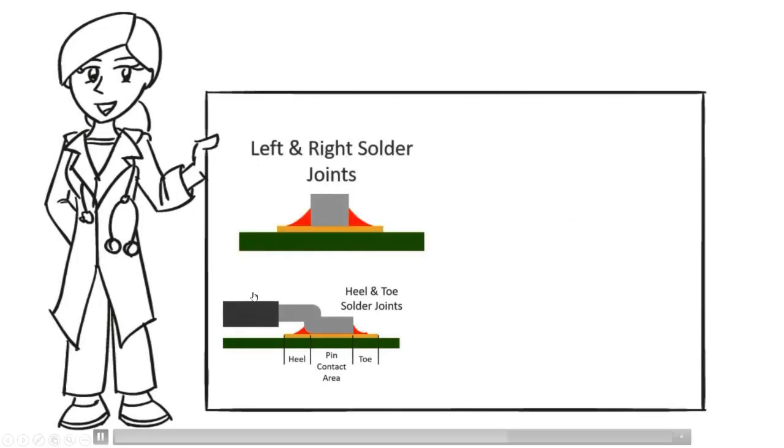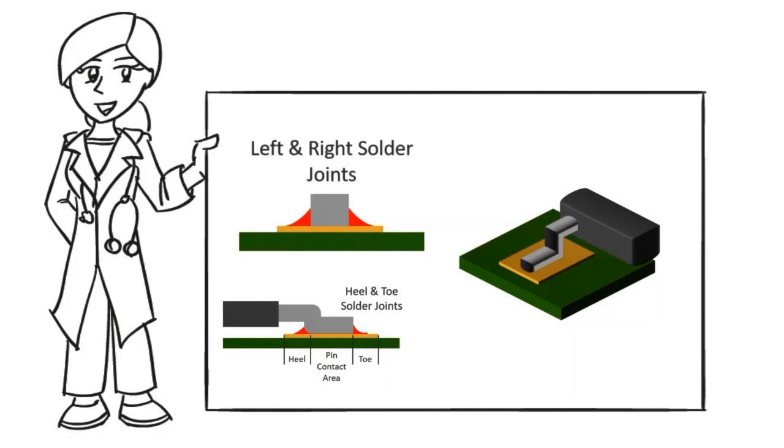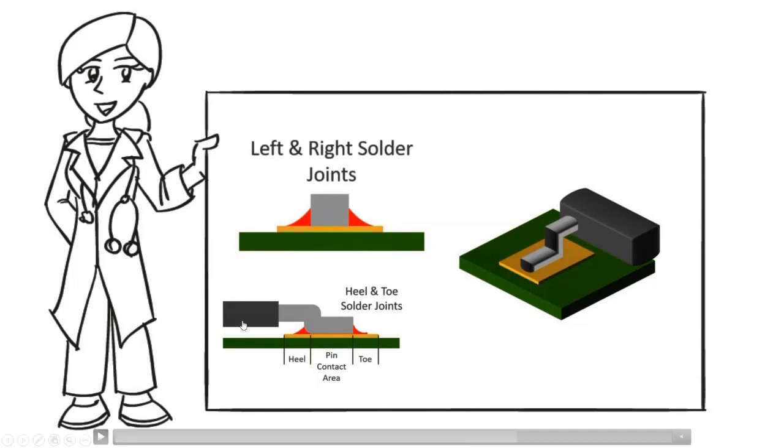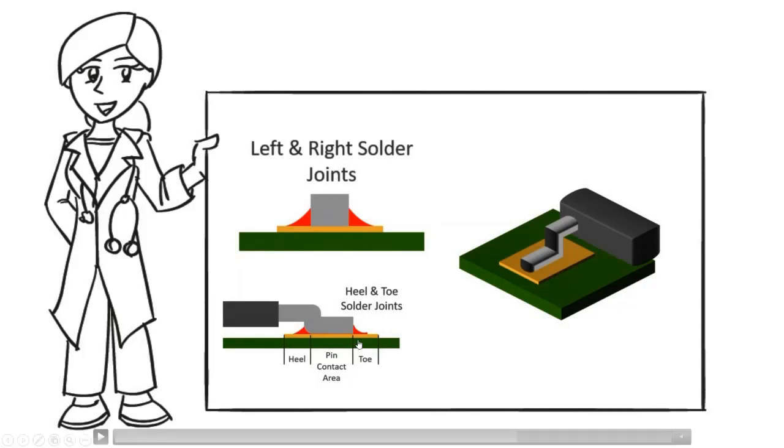The big difference is you have the ability with an assembly verification tool to go in and validate your solder joint and pad geometry to make sure you're going to get good, reliable solder joints during the assembly process. This is something that very few DFM tools have the capability of doing out there, and really no PCB design tool has this function.